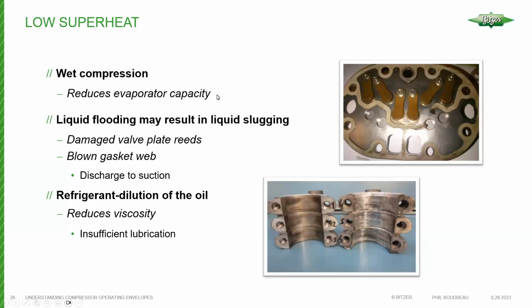So the setting of superheat at evaporators is very important. It should always be set so that you can hold a very stable superheat. And sometimes it's necessary to operate at a higher superheat in order to get a stable superheat.